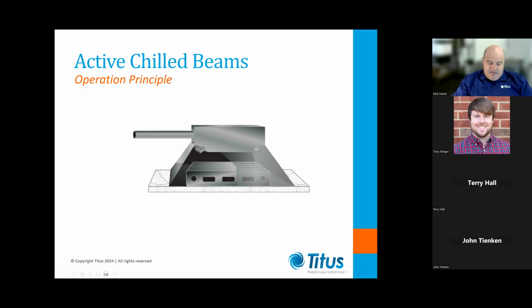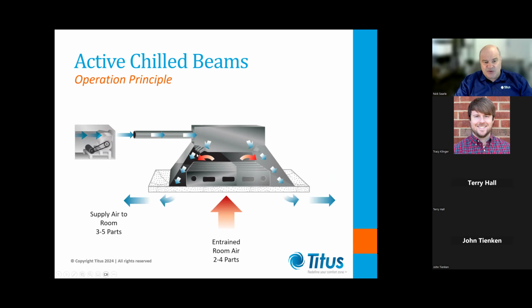So yeah, how it actually works is we're sending this air and pressurizing a primary air plenum chamber at the top here, and this centralized air pushes its way through these induction nozzles. Primary air leaves those nozzles at around about 3,000 feet per minute, and these jets cause a slight vacuum above the coil, which entrains room air across the heat exchange coil, where again we're applying sensible cooling or heating. That secondary air mixes with the primary air and is pushed into the room via typically 2 slots. So from the room side, they just look like wide slot diffusers, really.